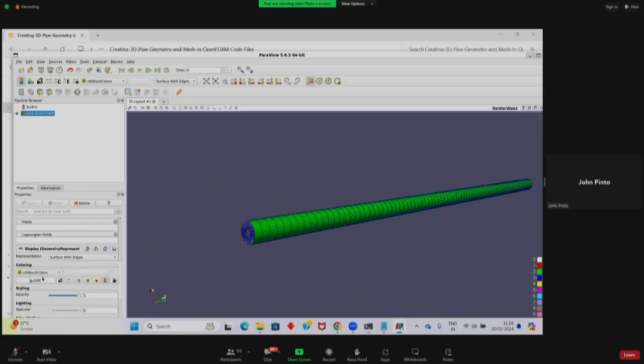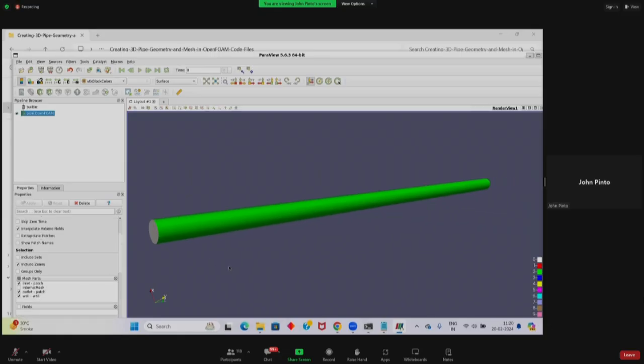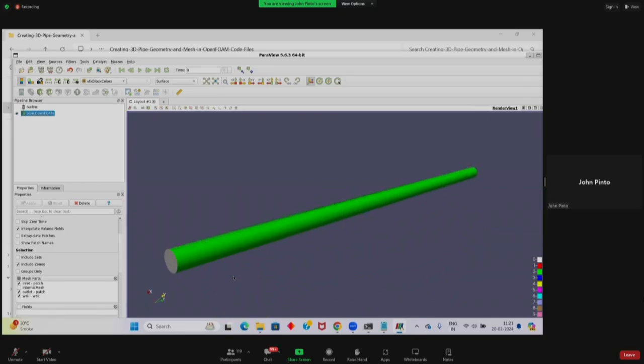I think here there is some edit feature, VTK block colors edit. So you can go over there and maybe edit specific blocks if that is your requirement. But right now, we have different colors for different blocks. So my inlet, outlet, and my walls are already colored in a different scheme. That scheme will already be there. They will be colored differently. So you have a red color, green color, and a white color.